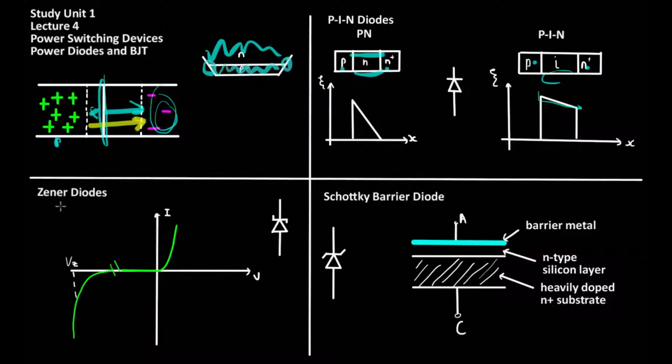The next diode under consideration is a special type of diode called a Zener diode. A Zener diode is a type of diode where the reverse breakdown voltage is designed to be purposefully low. In other words, the reverse bias which is required in order to get breakdown to occur across the Zener needs to be quite low before current will flow. Once the reverse bias across the Zener has exceeded the designed amount, which is normally a few volts, then the main breakdown mechanism is avalanche multiplication rather than Zener breakdown, after which the device is named.